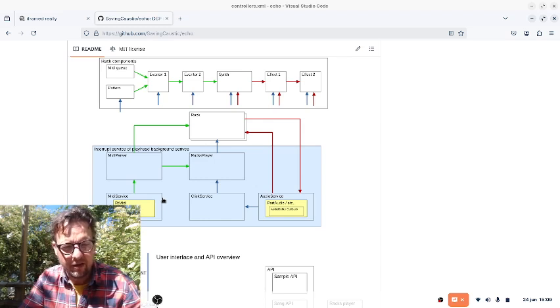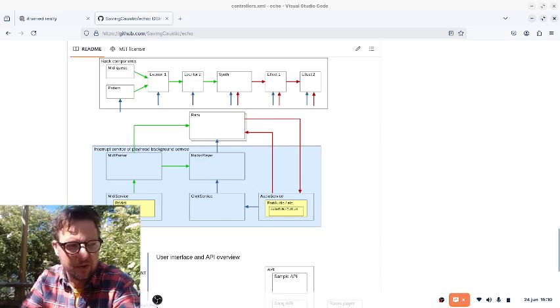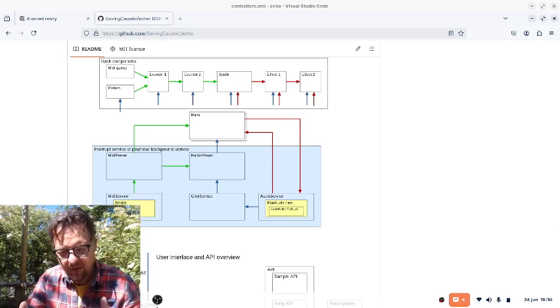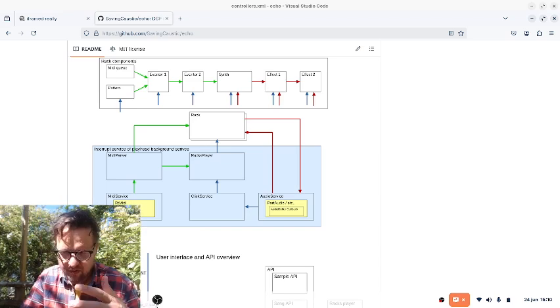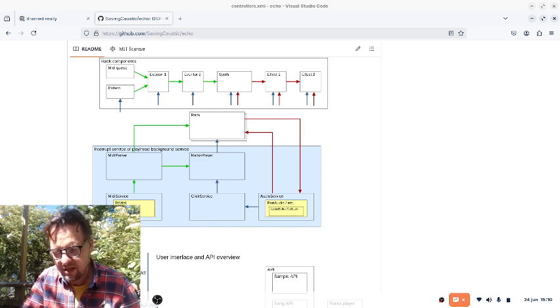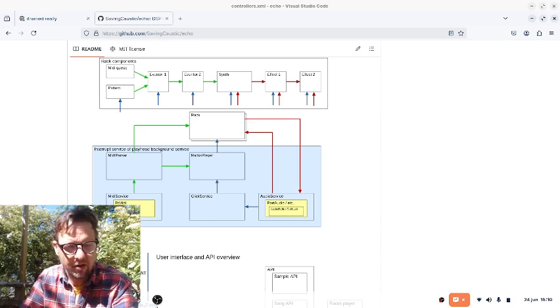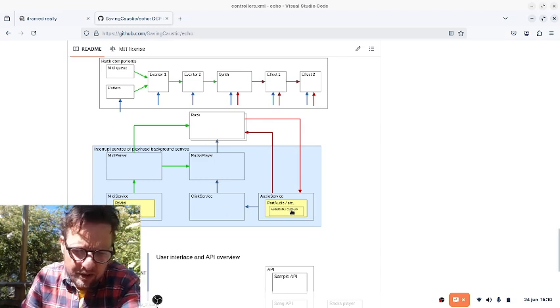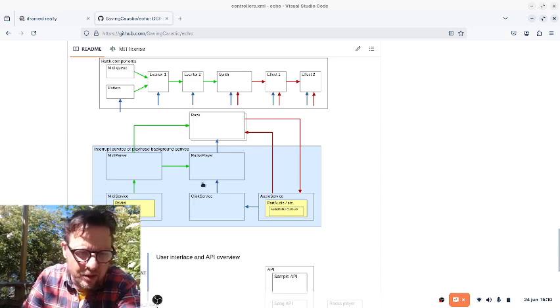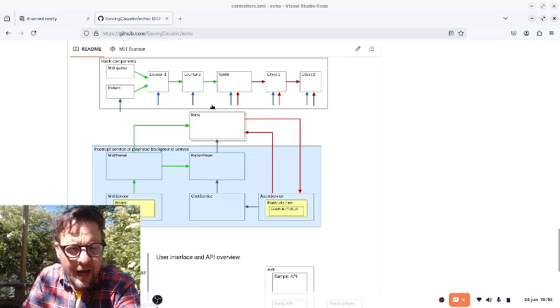For example, if you do audio recording, you need a buffer where the interrupt service can push the bytes coming in from the hardware, but outside the interrupt routine, these buffers are written to the disk or to the SD card or whatever. That should not be inside the interrupt routine.